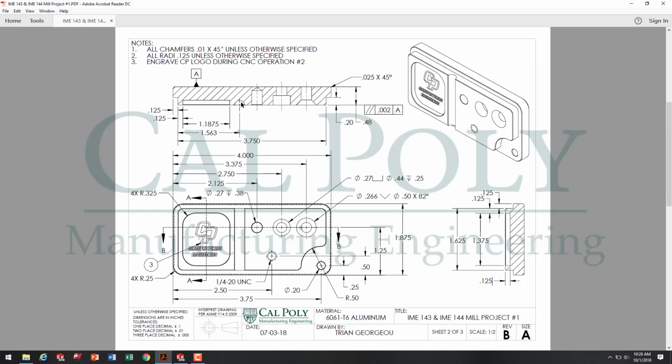So, in order to create this radial cutout, I'm going to look at this. This is 1.56, it ends up being 2.5. You'll see it's rounded up because we didn't need to go to a half thou for the precision. However, we're going to go ahead and do that in this model. Now, looking at the location, we've got the location and we've got the size. Actually, looking at this radius right here, and looking at the radii right here, unless specified, they're 1/8 of an inch. So we have to assume, since this one has not been specified, it's 1/8 of an inch in size.